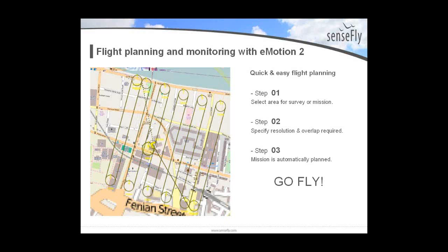And it'll then fly the mission. There are safeguards in there. One thing I failed to mention, when you're doing your pre-flight planning, you're picking a starting point and a home point, and your home point is where you want it to land. So when it's in flight, at any time you can tell it to come home, to land immediately.